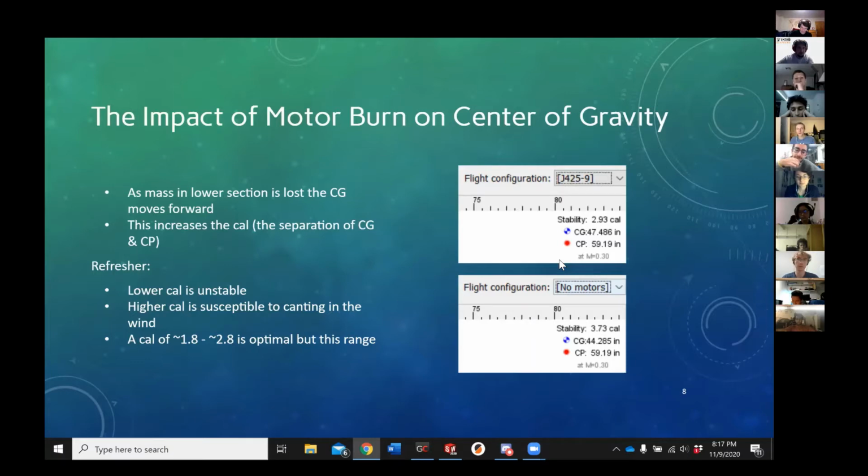So the thing there, though, is that the motor is a pretty significant weight in the rocket usually, but the motor goes away during flight. The motor is situated back down towards the tail, right? So if you get rid of the motor down there, it'll shift the center of mass forward in the rocket towards the nose cone, away from the center of pressure down by the fins usually. And that will increase the cal. So that'll make it more responsive to deviations between the axial direction and the velocity of the rocket.